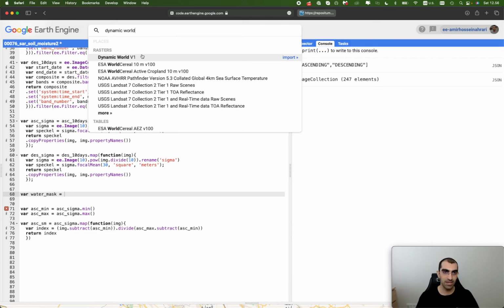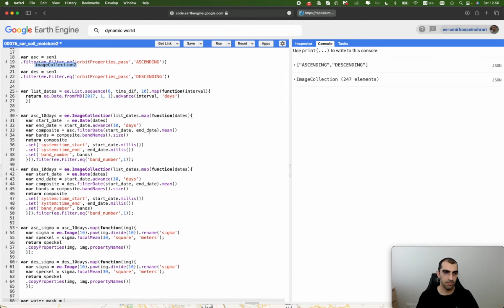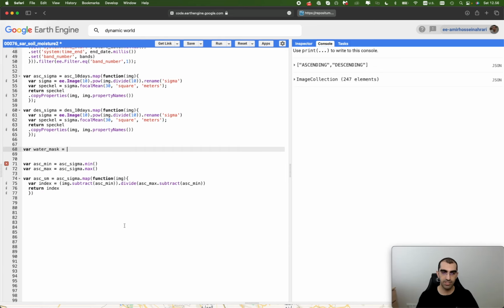It enables us to have access to dynamic land cover data with a 7 days interval based on Sentinel images for all around the world. Import it into the code, and then I'm gonna make a unique land cover layer for the region of interest, and then remove the urban area, remove the water body from that.